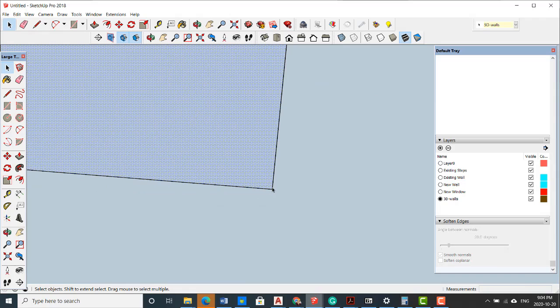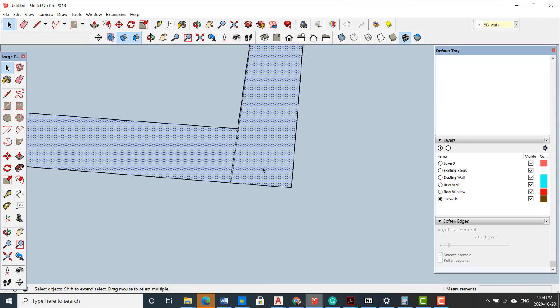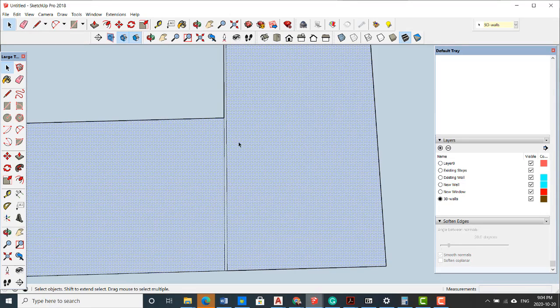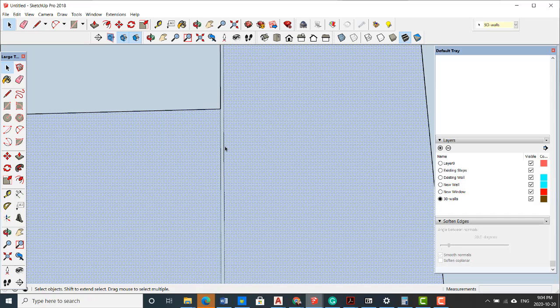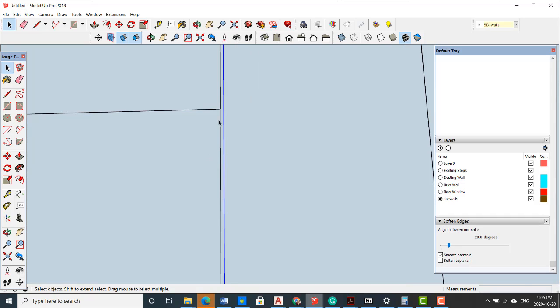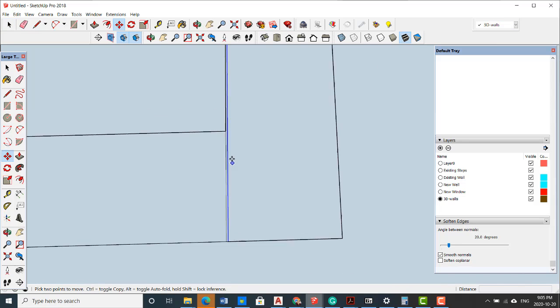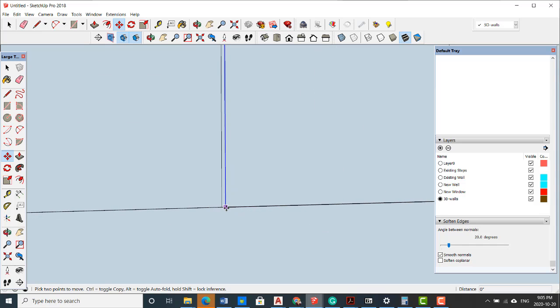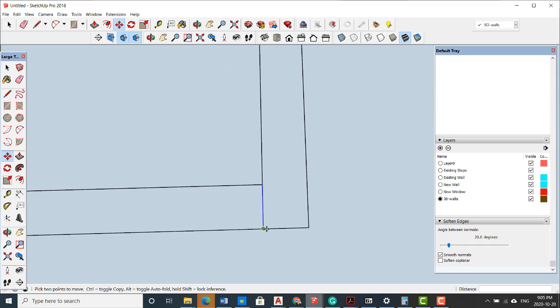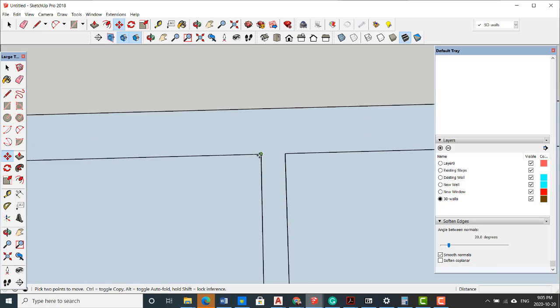Yeah, see, this wall in your AutoCAD is tilted, but I can just fix it. I just fix this one because see, this should be there. So I just use move, and I move this one maybe from here to here. Just let me double check this corner.